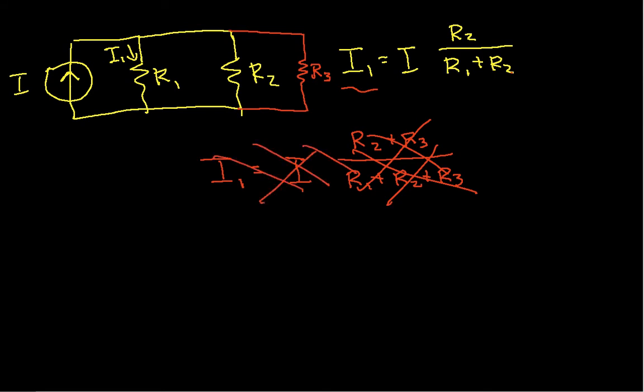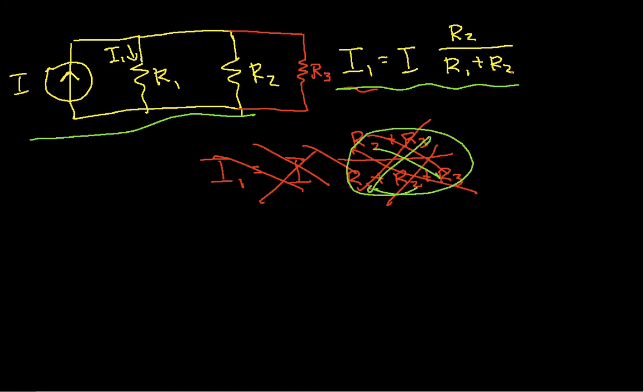It turns out, and you'll see this when we start talking about equations for parallel equivalent resistors, that you really can't do the current divider easily or tidily with more than 2 resistors. If you have a 3rd resistor, you have to be a little careful. So, again, the point I'm trying to make is that for the circuit that we've drawn in yellow, for this part of the circuit, this equation holds, and it's very useful. When I add a 3rd resistor, I'm tempted to do something like this, which again is a very bad idea.